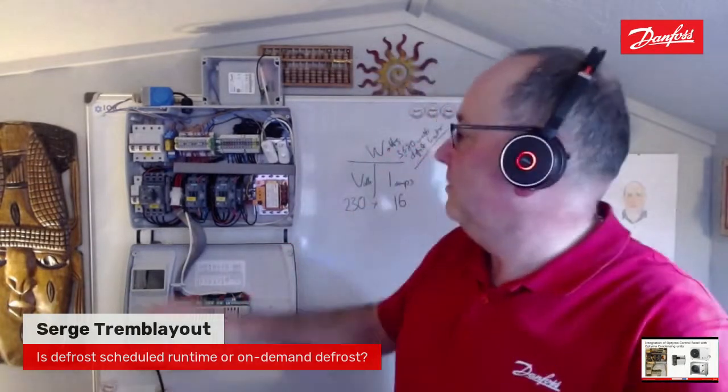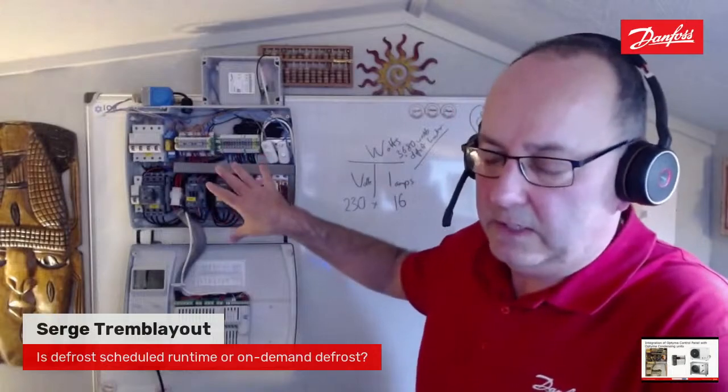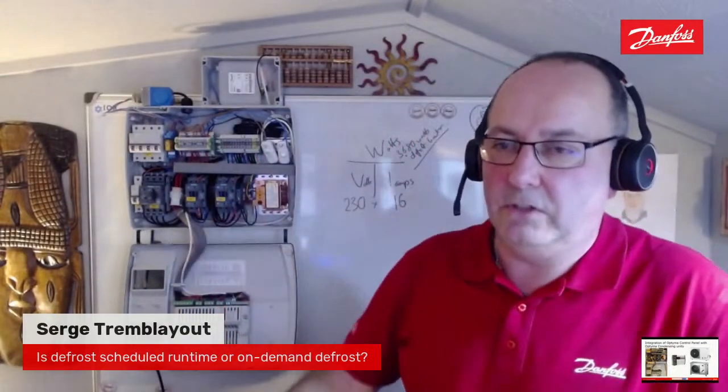Okay, well, we've got some more questions. So Sergey asks, is defrost scheduled runtime or on-demand defrost also? There's a couple of ways you can do it in here. You can have a schedule, which is what I've programmed in at the moment. Every 4 hours it will go on a defrost.